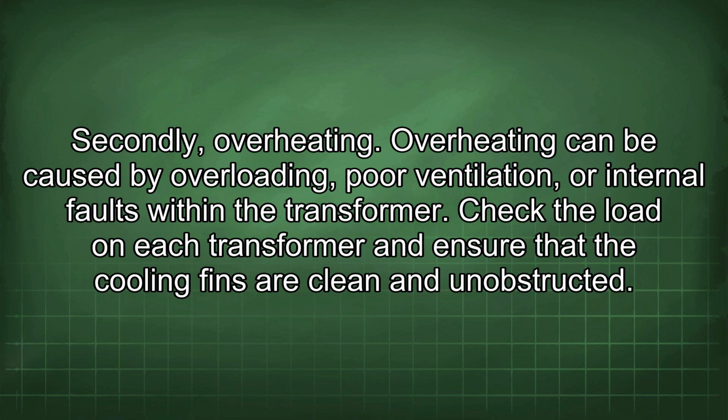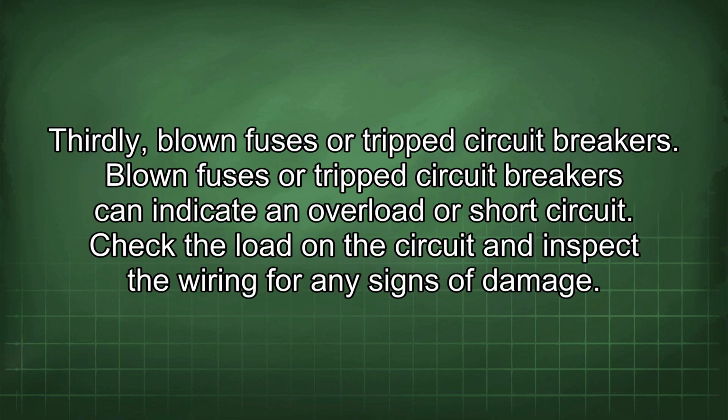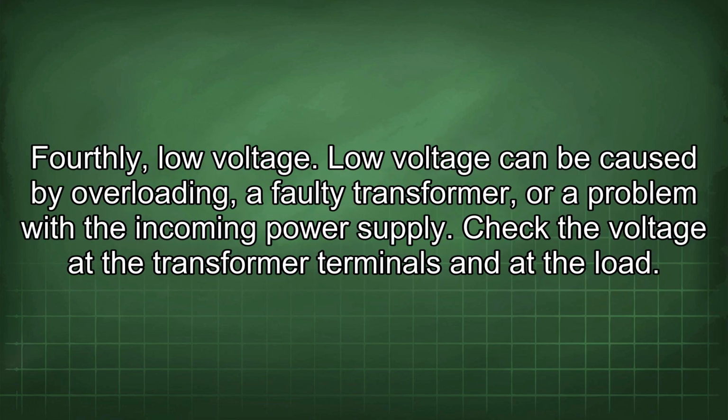Secondly, overheating. Overheating can be caused by overloading, poor ventilation, or internal faults within the transformer. Check the load on each transformer and ensure that the cooling fins are clean and unobstructed. Thirdly, blown fuses or tripped circuit breakers. Blown fuses or tripped circuit breakers can indicate an overload or short circuit. Check the load in the circuit and inspect the wiring for any signs of damage. Fourthly, low voltage. Low voltage can be caused by overloading, a faulty transformer, or a problem with the incoming power supply. Check the voltage at the transformer terminals and at the load.